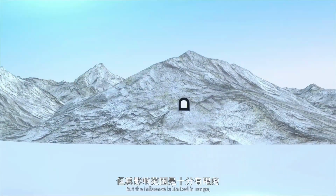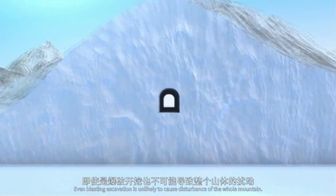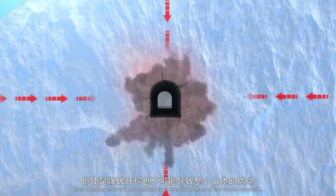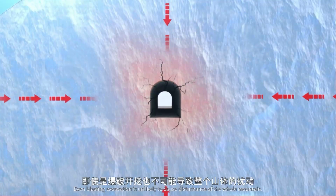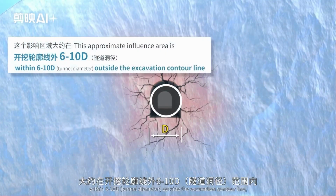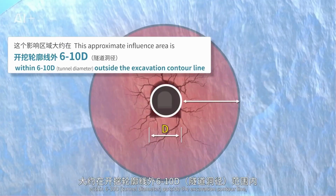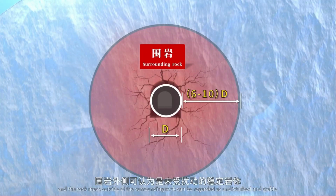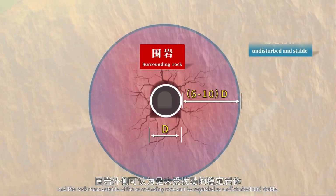But the influence is limited in range. Even blasting excavation is unlikely to cause disturbance of the whole mountain. This approximate influence area is within 6 to 10 times the tunnel diameter outside the excavation contour line. The rock mass in this range is called surrounding rock, and the rock mass outside of the surrounding rock can be regarded as undisturbed and stable.